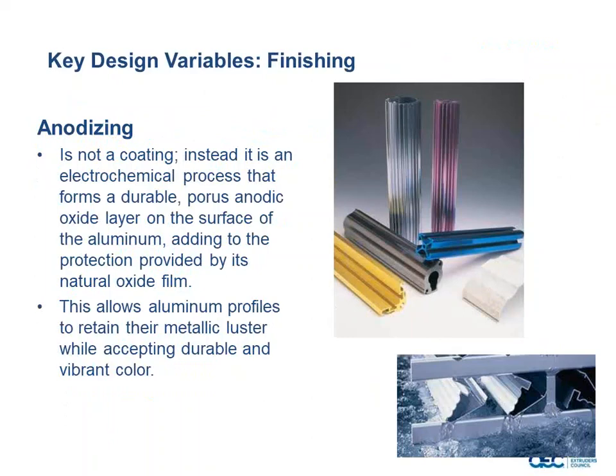Anodizing is a great solution for you. It's eco-friendly. It is not a plating. It's not something that's going to chip off. It's an integral part of the actual aluminum surface. And so you can get multiple colors. You can get it, as I call, sizzly colors, or just the standard clear satin anodize for you to use with your parts.